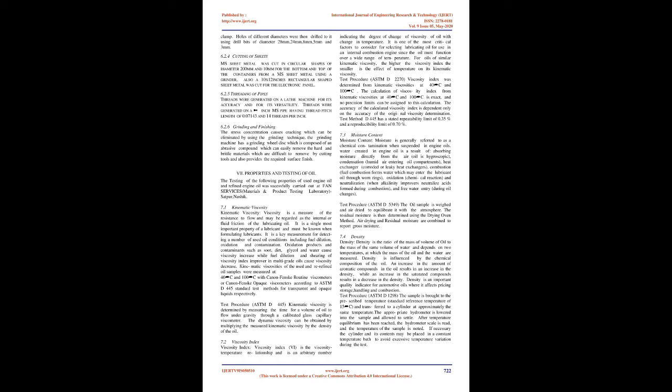Kinematic viscosities of the used and re-refined oil samples were measured at 40°C and 100°C with Cannon-Fenske routine viscometers or Cannon-Fenske opaque viscometers according to ASTM D445 standard test methods for transparent and opaque liquids respectively. Test procedure, ASTM D445: kinematic viscosity is determined by measuring the time for a volume of oil to flow under gravity through a calibrated glass capillary viscometer. The dynamic viscosity can be obtained by multiplying the measured kinematic viscosity by the density of the oil.